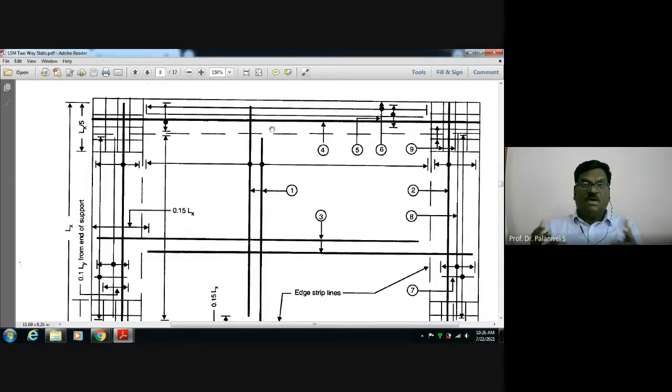Now the area of steel provided is reduced. How do I compensate for it? I cannot introduce another 12 mm bar in between. Again, whatever area of steel is provided, the same area of steel will come here. This author has used 12 mm dia bar. In between these two 12 mm dia bars, which are spaced at 400 mm, I can introduce some 10 mm dia bar or 8 mm dia bar. So my area of steel provided for 1 meter wide, for unit length, will be the computed one, the area of steel required in that locality.